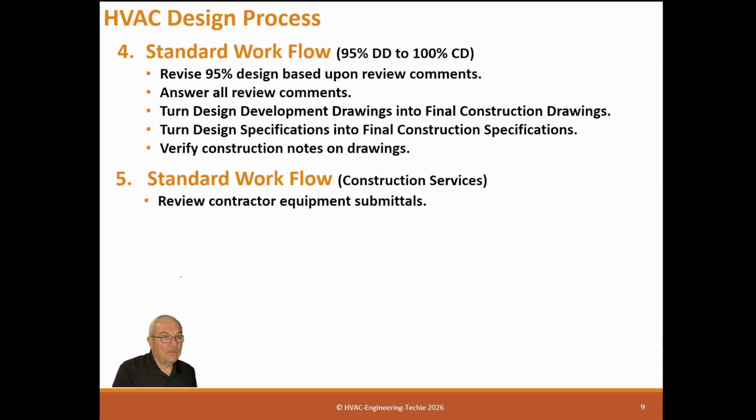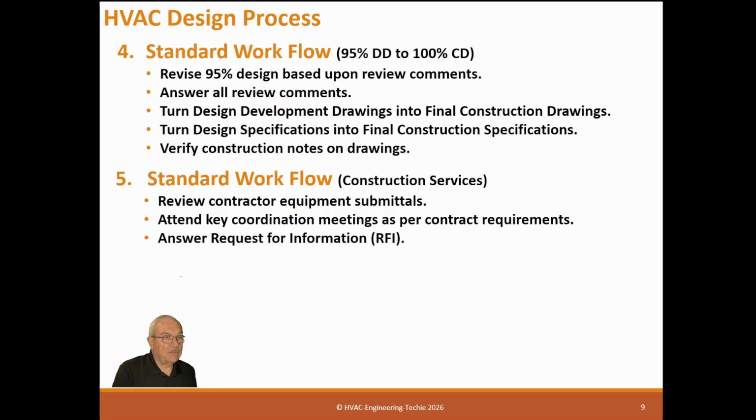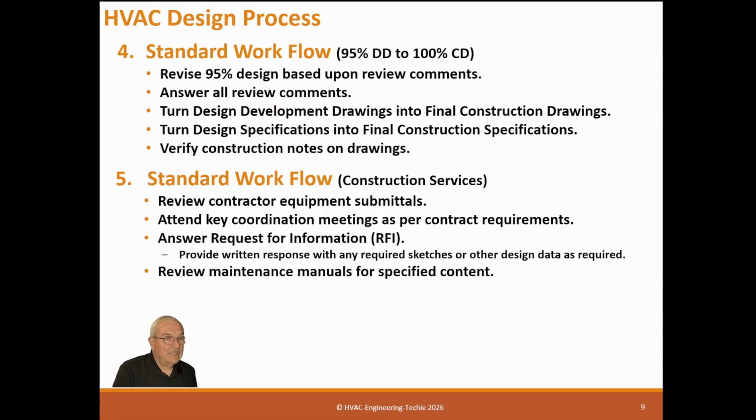Standard workflow for construction services. So if your contract calls for the engineering firm to provide engineering services, there are certain things you do during the construction of the document. And these will be different depending on your contract. Review contractor equipment submittals. That's almost always included. Attend key coordination meetings as per contract requirements. Answer RFIs as they come in, request for information. Provide a written response with any required sketches or other design data as required to answer the RFI.